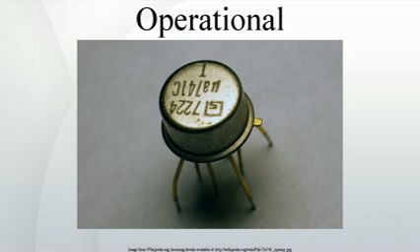Stability. Associated with the bandwidth limitation is a phase difference between the input signal and the amplifier output that can lead to oscillation in some feedback circuits. For example, a sinusoidal output signal meant to interfere destructively with an input signal of the same frequency will interfere constructively if delayed by 180 degrees, forming positive feedback. In these cases, the feedback circuit can be stabilized by means of frequency compensation, which increases the gain or phase margin of the open-loop circuit.